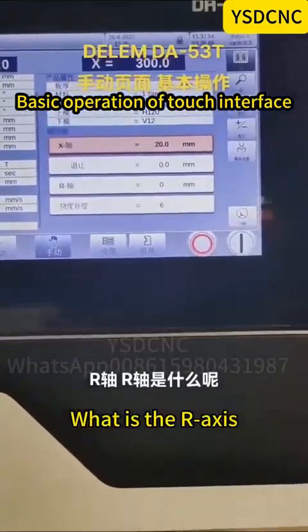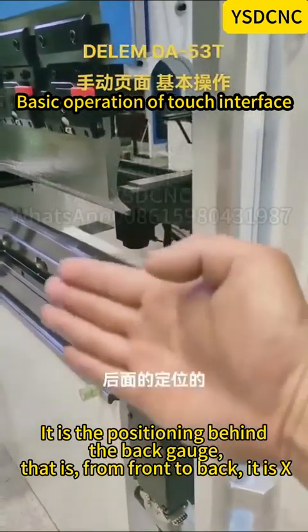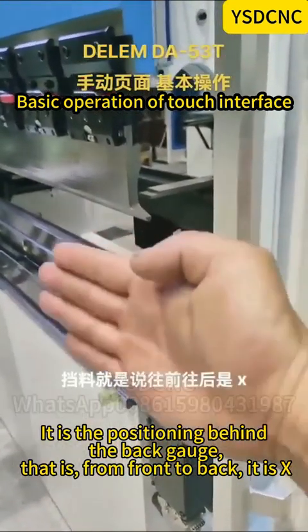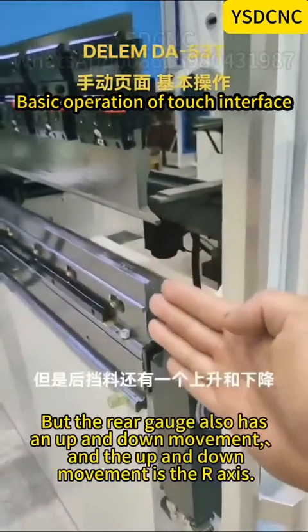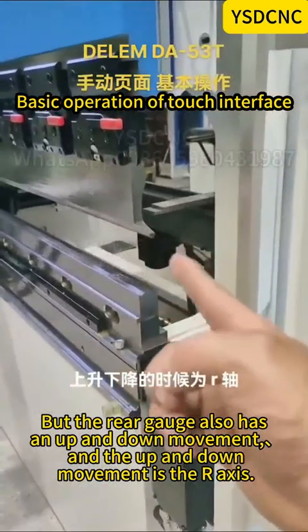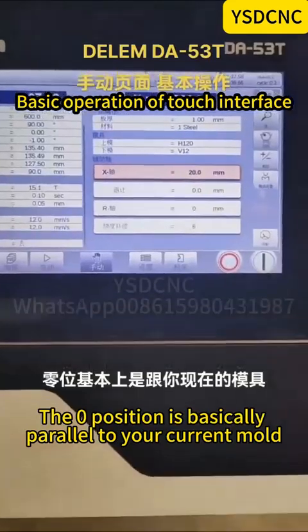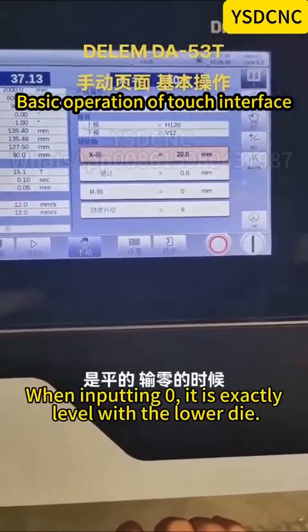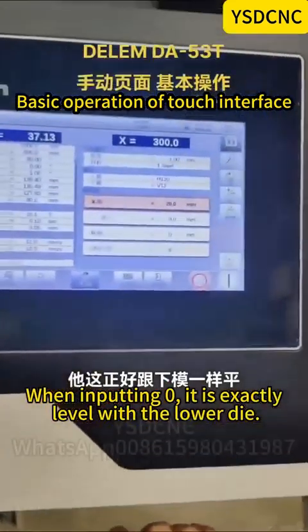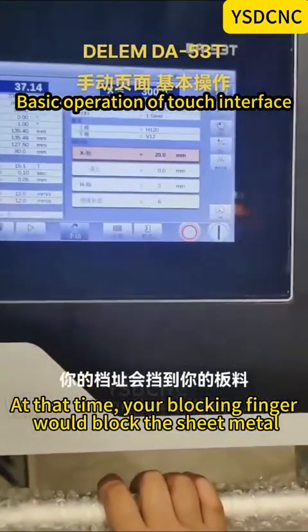What is the R-axis? It is the positioning behind the back gauge, that is, from front to back, it is X. But the rear gauge also has an up and down movement, and the up and down movement is the R-axis. The zero position is basically parallel to your current mode. When inputting zero, it is exactly level with the lower die. At that time, your blocking finger would block the sheet metal.